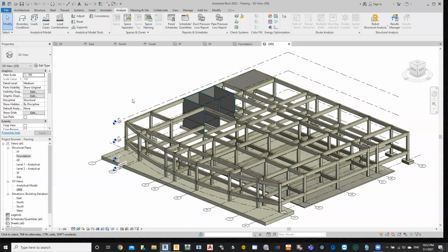Sir, can we select all the grids to draw the slab? It is not recommended. We have to draw one by one. Especially if you are having, for example, sunken slab and different loading. Because if you are transferring it to Robot later on, it will be read as one slab. If you have a uniform loading for everything, then you shouldn't have a problem.